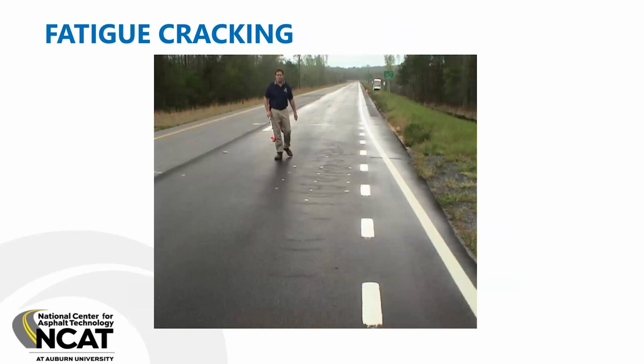This is what bottom up fatigue cracking looks like. This is actually the thinnest pavement that has been built on the track. It was part of a 2003 structural experiment. We had 2 sections that were only 5 inches thick, 1 full depth neat asphalt, 1 full depth polymer modified asphalt. When you have a thin pavement, the bending at the bottom of the pavement in response to passing loads produces higher strain magnitudes in the longitudinal orientation, the direction of traffic. And that means that bottom up fatigue cracking starts in the transverse direction at the bottom of the pavement.